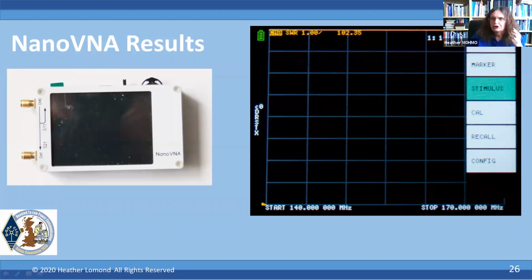You'll still get an impedance reading and it'll still be correct. But if you remember what I was saying about what the beam pattern is, i.e. is the balanced line actually balanced? And what are the losses in things like coax and so on, and where they are? Again, you can't get much information about that sort of thing with an antenna analyzer.